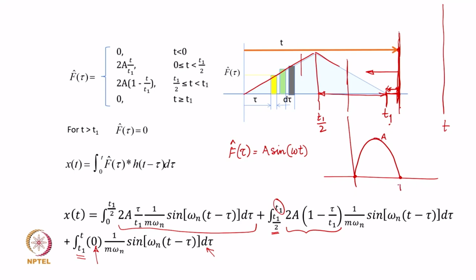What will omega be in this case? Omega is not omega n; it is not related to your vibratory system, it is an external excitation. So, omega would obviously be 2 pi over total time. Now, total time is going to be 2T if T is the half time of the sine wave. So, pi over capital T will become your omega.